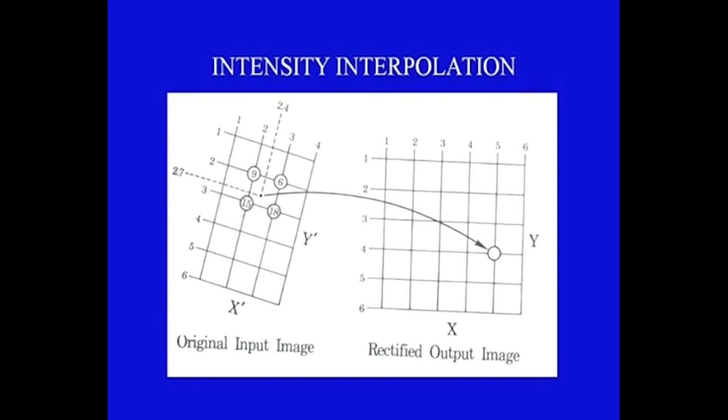In order to do so, one will find out the distance between the pixel center and the superimposed position of the rectified output image pixel. Whichever distance is the minimum, that particular pixel's brightness value will be adopted for the new pixel in the rectified image.